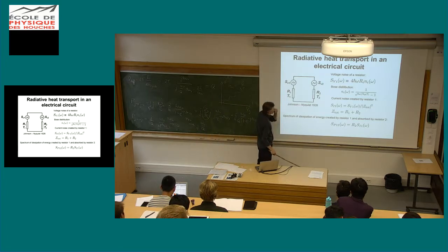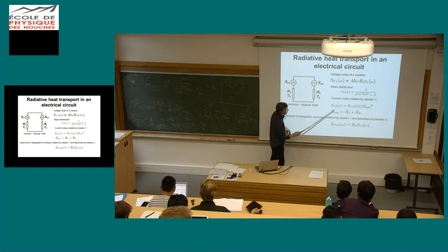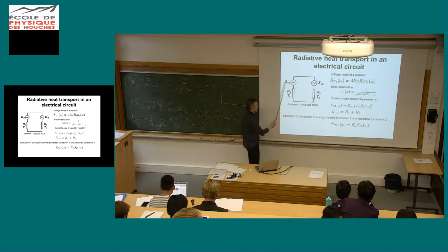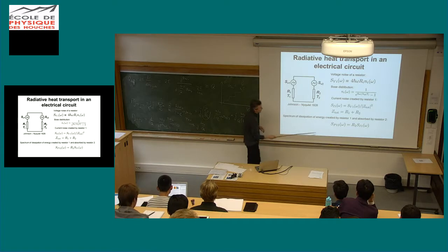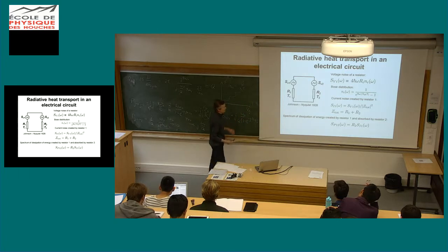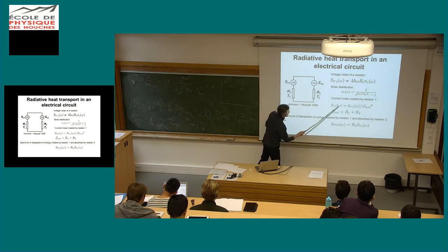And both of them do the same, of course. So we can consider these as two independent sources of noise. The current noise that this resistor induces to the circuit at temperature T1 is given by this voltage noise divided by the total impedance of this circuit squared. And this, of course, is very simple. In this case, it's just the sum of the two resistances. And then the spectral power of this noise at a certain frequency is like I squared R. So it's the power that it is dissipating in this second resistor: R2 times this current noise squared.